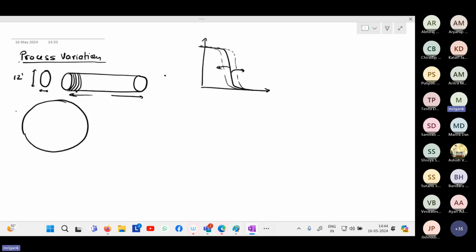And on this thin circular disc, we fabricate the ICs. The way it is fabricated is we print the ICs in this circular disc. We divide this circular disc into multiple segments of, say, given dimension, and the design that you have implemented will be copied into or printed into each of these sections, and then it will be cut out.